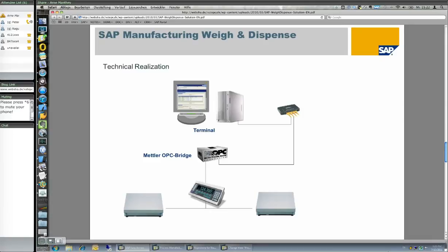Currently, we are using it in Singapore. We do have different equipment, not only scales, but also blenders, thermometers, and all the stuff where we are trying to get values out of the PI sheet. In the PI sheet, we have a button where we read a tag from any OPC-speaking device and transfer it automatically into the PI sheet and do our checks on it.